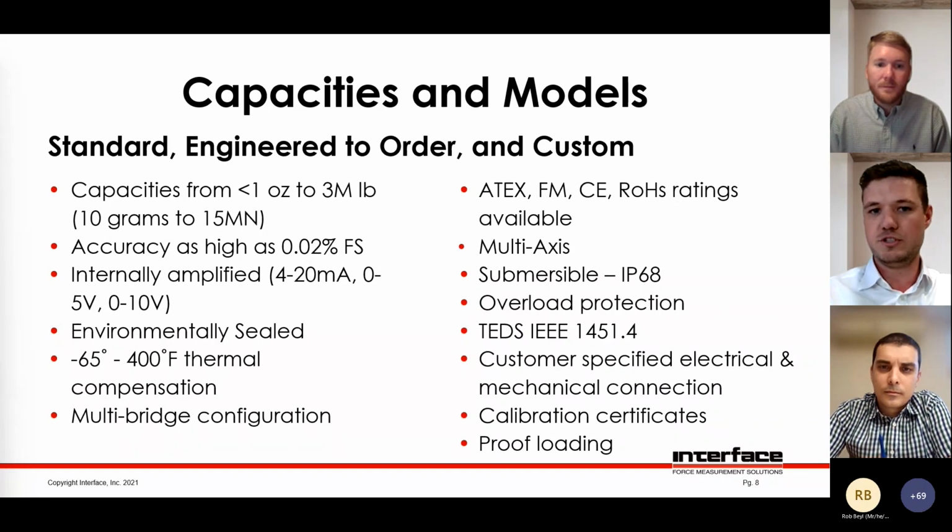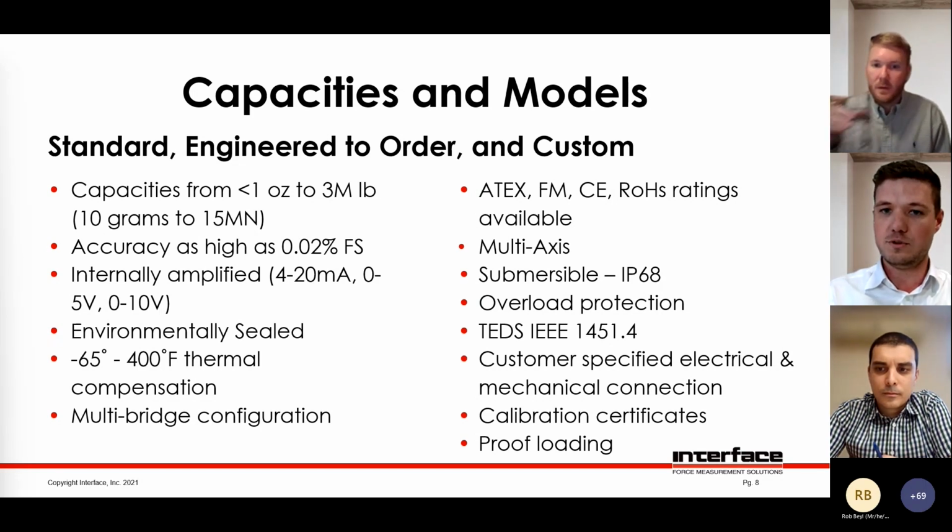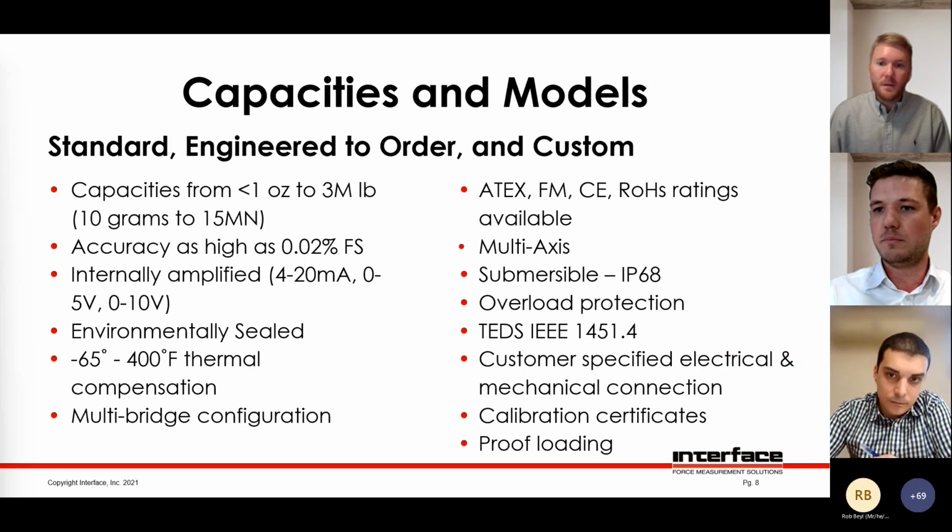TEDS stands for Transducer Electronic Data Sheet, and it's a small chip that can be fitted to the connector of the load cell or in the cable somewhere, and it holds the calibration data for the load cell. The data is held in an IEEE standard, and if you've got a TEDS compatible indicator electronics, it can read the data on that chip and scale the electronics specifically for that load cell's calibration data.